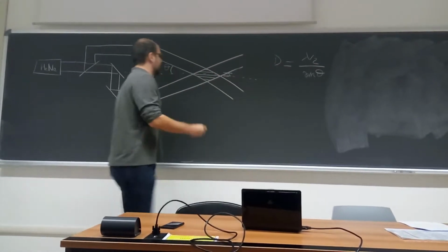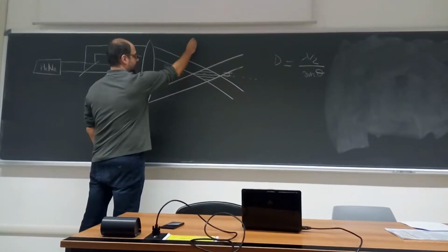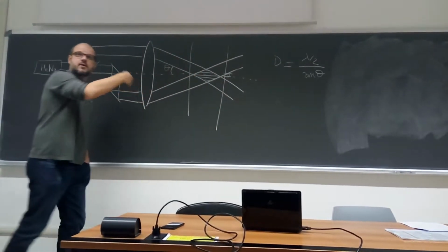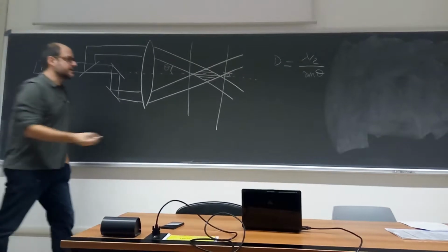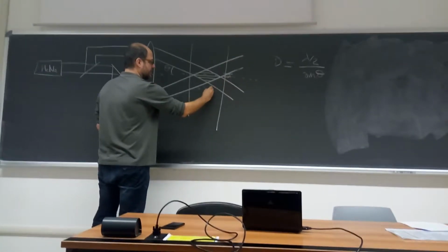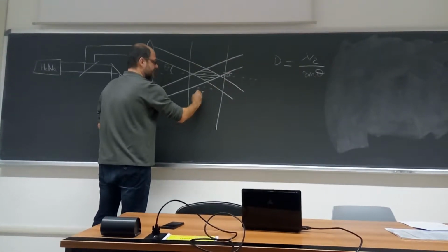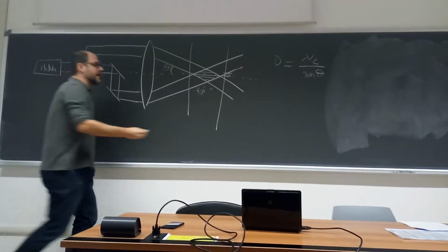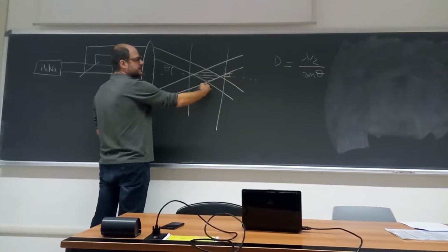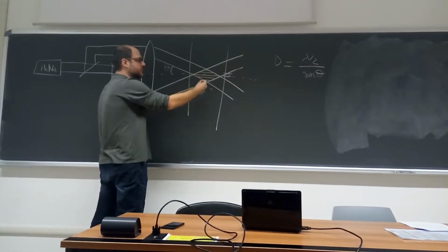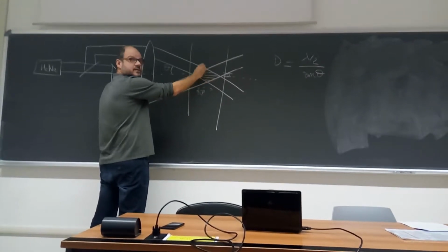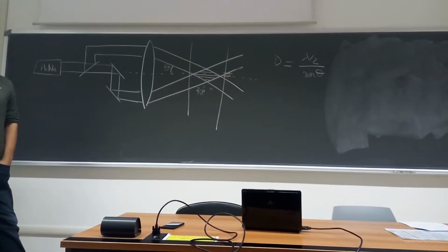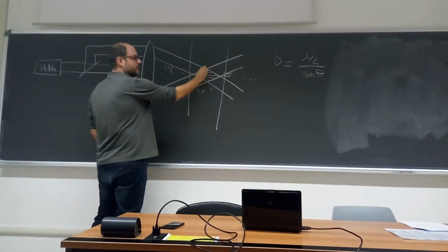Now, what is the principle? Let's suppose that here we have a liquid or a fluid that is moving. What we do is insert particles in this fluid. For example, these are moving with a velocity in this direction. When they cross the fringe zone, the light is scattered from the zone in which we have the maximum of light.